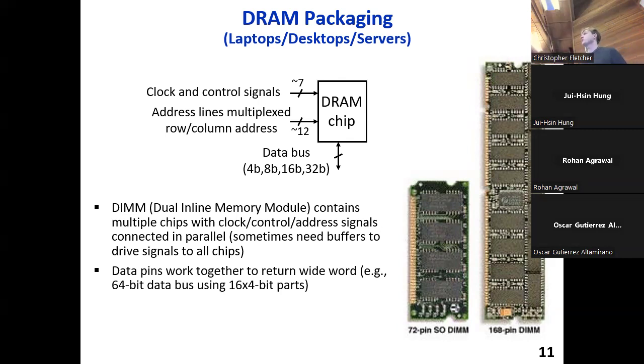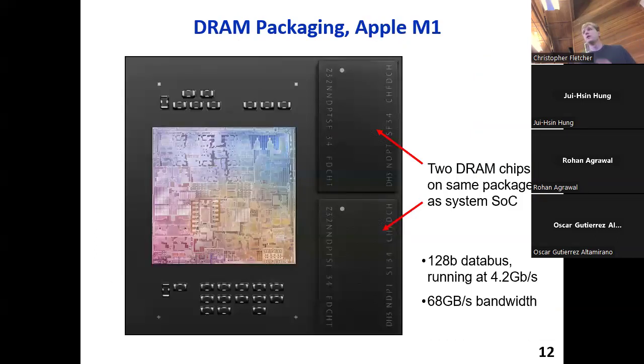You put 12 bits of address in one cycle and send that to the DRAM, and then you're going to put more bits of address on those 12 bits later. And so you're kind of serializing the address out. What that allows the DRAM to do is have fewer pins, which is better from an area perspective, which helps with the whole density argument. So really, they're dialing all dimensions up for density at the cost of access latency, because of course, having all of the address bits there at time one, you could potentially get your data out sooner.